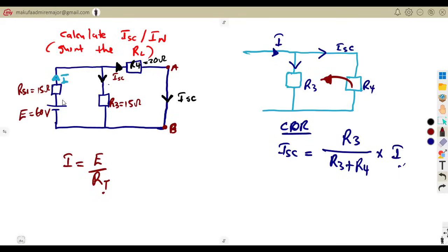Guys, this is our circuit here, like we can see it. Here there's a supply. So meaning to say, we consider the current flowing here, when it is branching in, remember the concept of parallel. The current is flowing and when it meets this junction, another one goes here, another one here. So it means R3 and R4, they are in what? Parallel. They are not having the same current. The current is going to be subdivided, so they are in parallel.